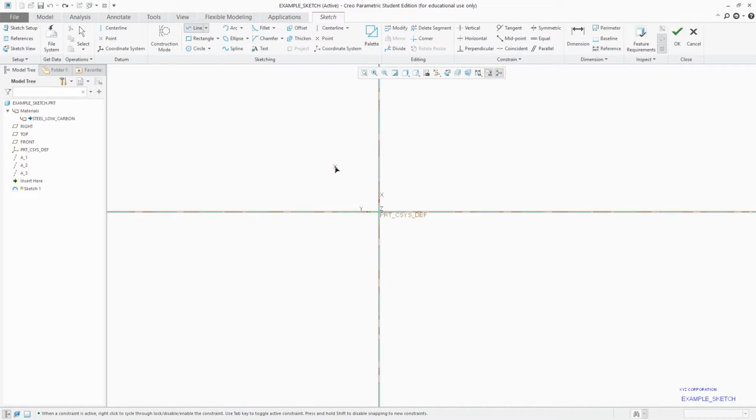Now click anywhere. Let's say for example I want to make a triangle. Now you can see here I am getting a kind of polar tracking. In AutoCAD we say polar tracking. So here you can see our line is getting snapped at 0 degree, and you can see there is a green horizontal symbol in a square just on the right side of the cursor.